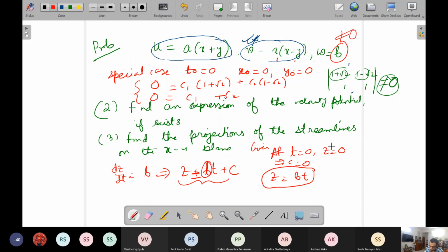The consideration from which I was talking about first, about the particle staying at the origin, is based on what happens in the xy plane, because our differential equation which we solved was y as a function of t and x as a function of t. We did not bring in w, and because of the interdependence of x and y components of velocity, and z component being like a constant, this is a very interesting mathematical situation: although it's a three-dimensional flow, it can be thought of as something in the xy plane superimposed by something along the z-axis.